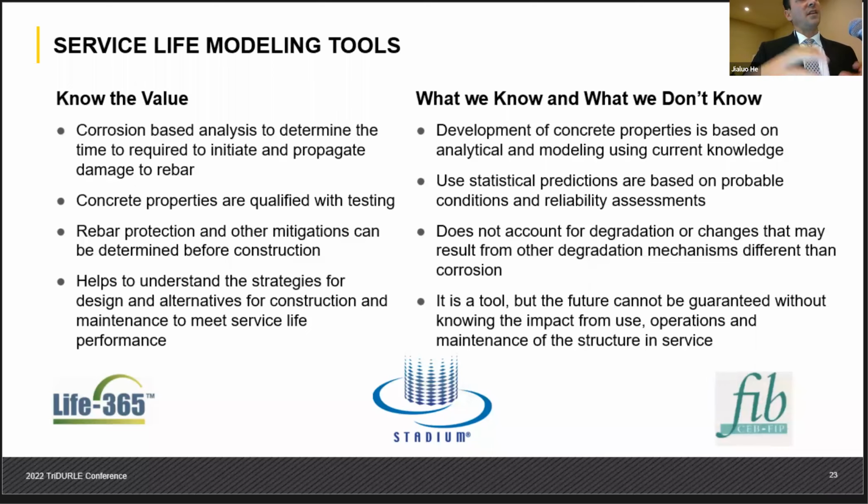So when you look at service life, it's a corrosion service life. It doesn't tell you what's going to happen with the freezing and thawing damage cycling that is happening, or a sulfate attack condition, or if you have ASR, what's going to happen in 100 years. None of that is done in a service life analysis. You're looking at corrosion-based issues, okay? And again, I reinforce, it is a tool, okay? So you cannot guarantee the future.